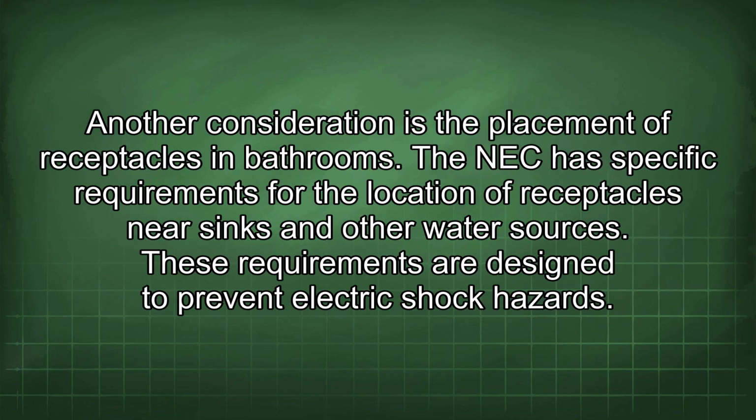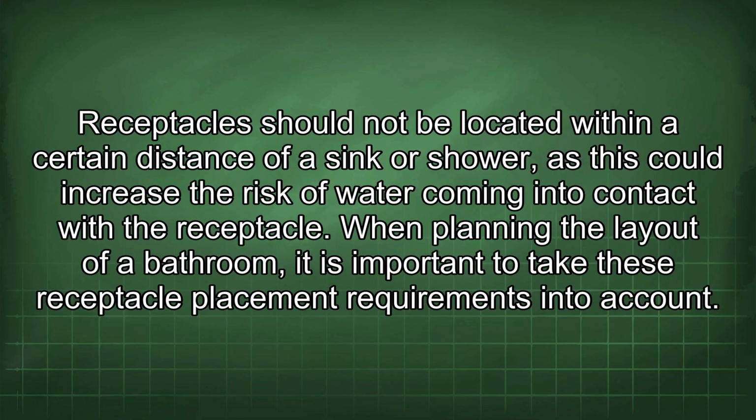Another consideration is the placement of receptacles in bathrooms. The NEC has specific requirements for the location of receptacles near sinks and other water sources. These requirements are designed to prevent electric shock hazards. Receptacles should not be located within a certain distance of a sink or shower, as this could increase the risk of water coming into contact with the receptacle. When planning the layout of a bathroom, it is important to take these receptacle placement requirements into account.